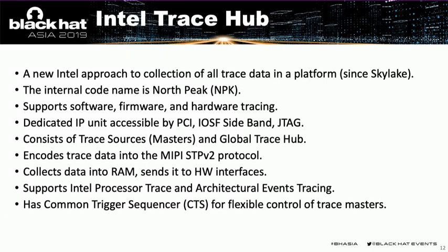Intel Trace Hub is Intel's answer to the need to collect all of the platform's trace data in one place. Its internal code name is NorthPeak, and it collects data from hardware, software, and firmware sources. It is integrated in all modern SoCs and PCHs, starting from the Apollo Lake Atom SoC and the Sunrise Point chipset for Skylake-based platforms.